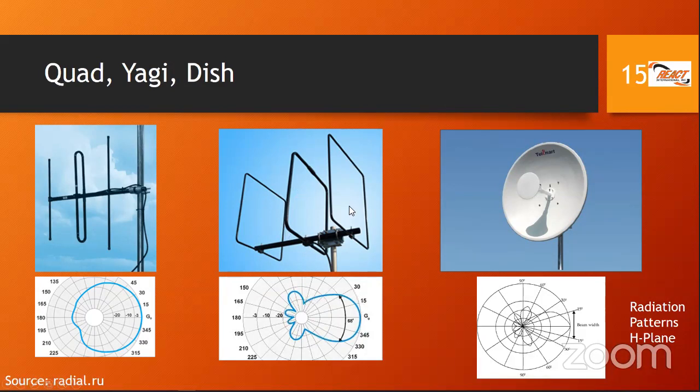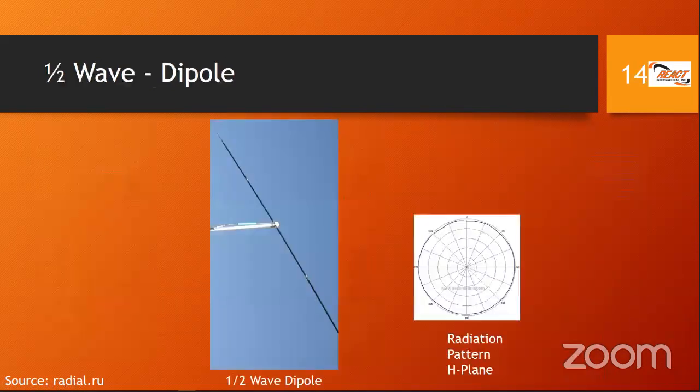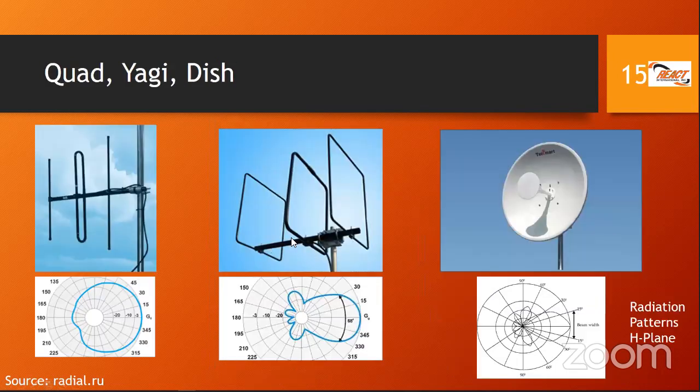Again, like the other antenna, please think of this antenna as pointing in the opposite direction. All right, so this is the radiation pattern. Notice the directivity of the antenna. This is comparing and contrasting with, let's see if we go back to it here, the omnidirectional antenna where the signal radiates in all directions just about equally. Notice with the directional antennas, you have a strong signal in a particular direction and it's weaker off the sides and to the back.